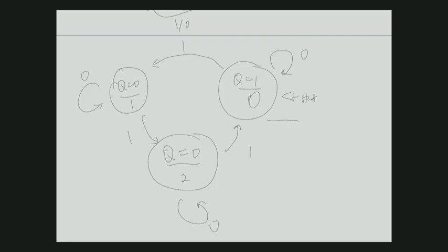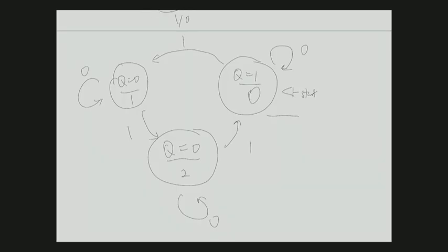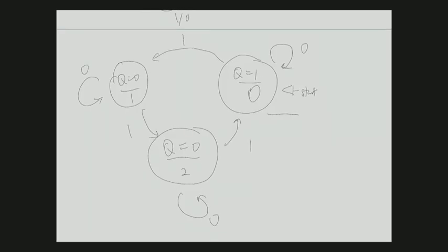Could you keep it here, and I want to talk a few more words about your design. So we need 3 states because there's 3 different scenarios we need to remember: 0 mod 3, 1 mod 3, 2 mod 3, and these are different states. You have to remember them, so you need 3 states. And then Eric also defined an initial state. That's when you start the machine, essentially we've seen nothing, so like 0 mod 3. Right? And then remember there are 2 additional things we need to design.